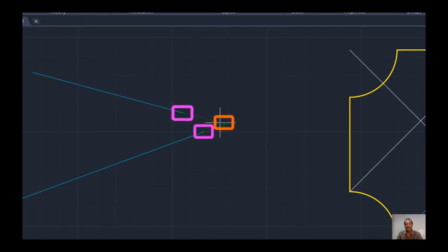If you extend these two lines, it will meet exactly that particular point where it shows the cross mark. Now you press the button, the particular intersection point will be taken. This is called apparent intersection. That means these two lines will go and intersect or meet at that particular point. Just click, you will get the circle. If you really extend these two lines, it will meet exactly the center of the circle. You can check now, both lines are intersecting exactly at that point.